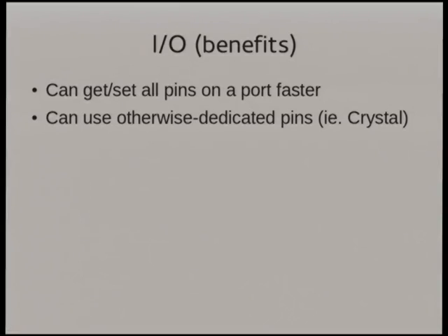One of the other neat tricks that you can do is, because we're not using a crystal on this chip anymore, you can reuse those pins for input and output. And you probably should never do this, but it turns out you can also use the reset pin for output. It sounds really crazy because you've got all these pins, but on the 8-pin devices, that's actually kind of handy because you've only got a really limited number. Once you've got a power and a ground and a couple of input and output pins, you run out of pins really quickly.